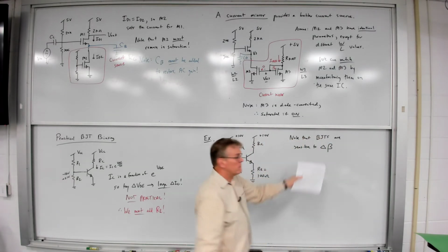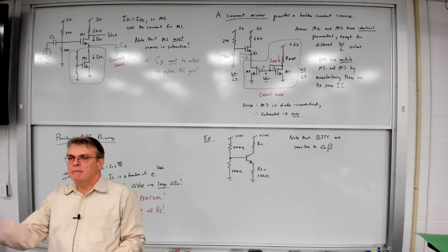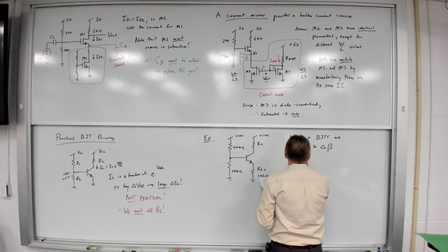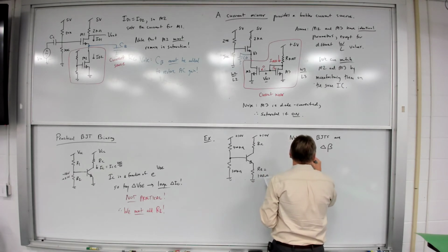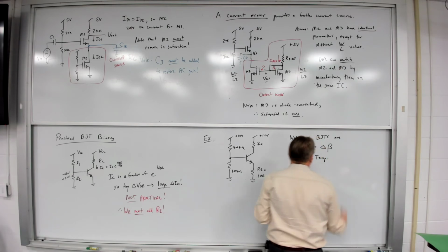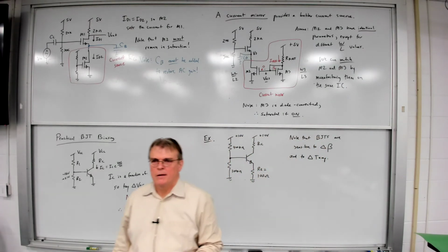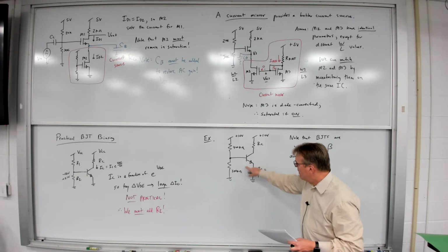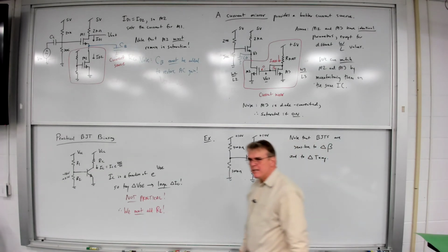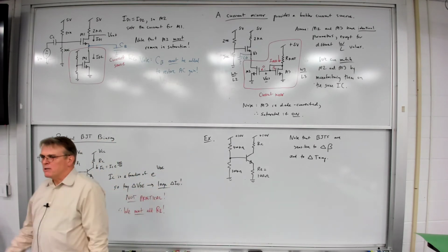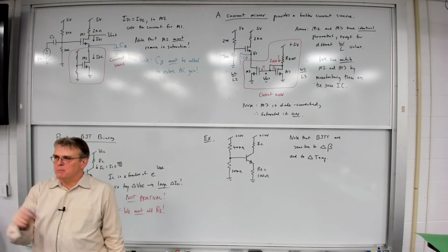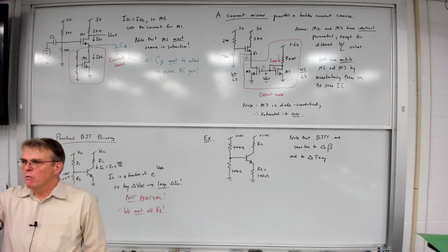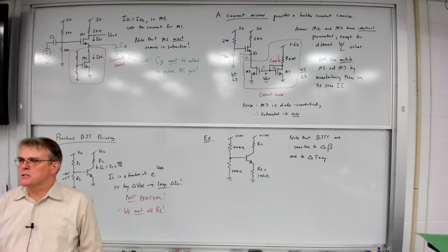transistors are going to be sensitive, first of all, to changes in beta. Beta varies, the current gain. So that's going to change. And also to changes in temperature. And why is that? Okay. Well, keep in mind, there is a diode between the base and the emitter. There's a p-n junction. And we talked about this before. There is a temperature dependency of -2 millivolts per degree C for the voltage across a p-n junction given constant current.